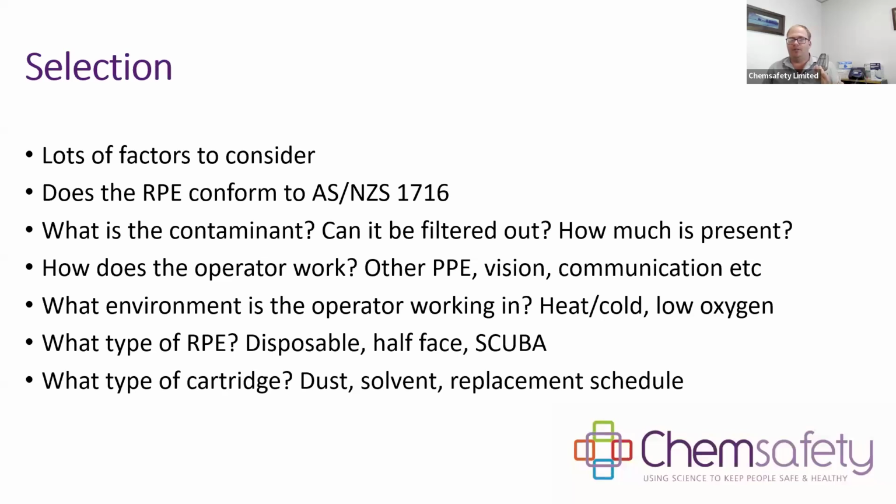Another thing with solvent filters, they have a shelf life. So on the packaging, there will be, once open, this will last for a maximum of this time. Quite often you'll find that your exposure means it lasts less than that, but you should write on them the date that it was open so you know which date at the very max that it has to be chucked out and replaced.